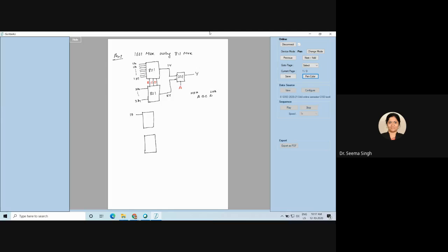Again, I have my 1D0 to 1D7 here, and I have 2D0 to 2D7 here. This forms my 16 inputs. And I have a 1Y here and a 2Y here. Both are my 8 is to 1 mux. And as we know, our select lines are always LSBs.